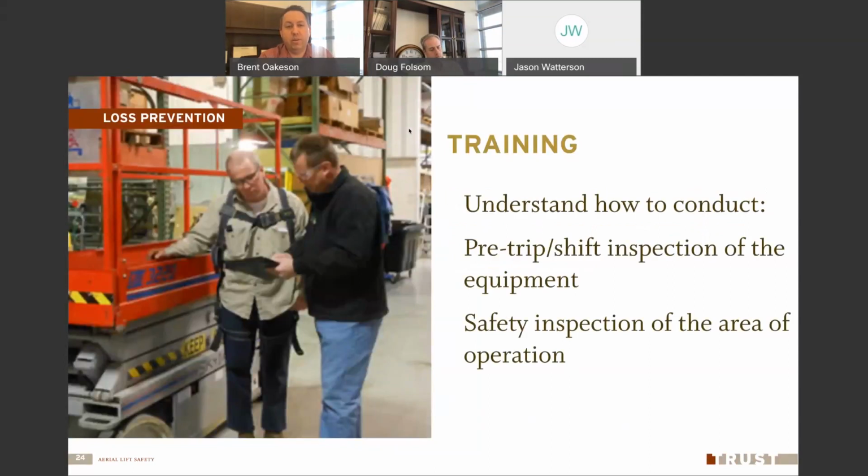As far as training goes, you also want to be trained on how to do a pre-trip or a pre-shift inspection of the equipment. That should be done each time before the equipment is used. You want to have a good inspection and check it out, because you don't want to risk going up in the air and putting your life, your body and your health at risk if something is going to go wrong and fail on the equipment. So that pre-trip inspection is very important.